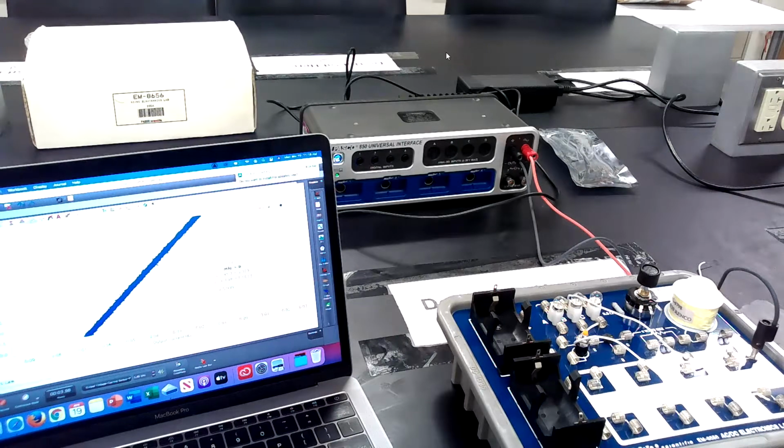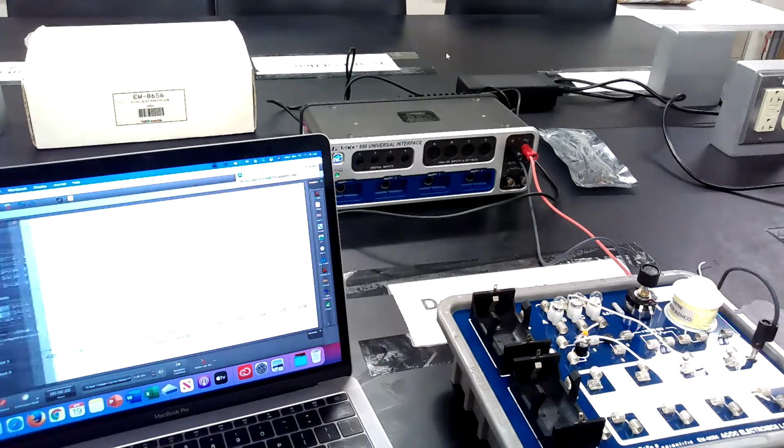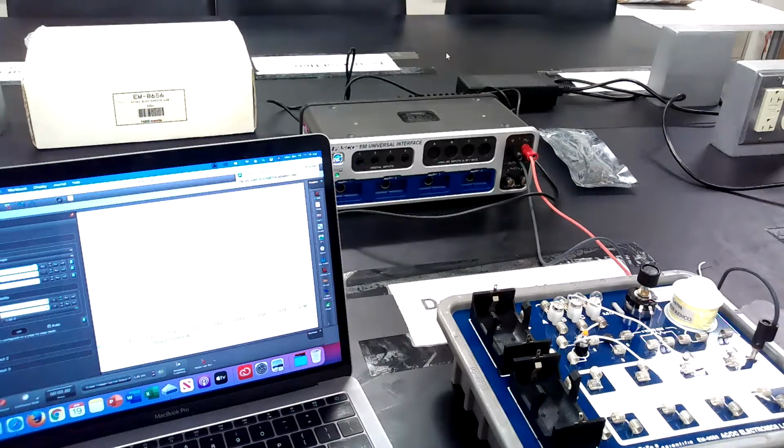All right. So let's take our previous result. We are going to erase that. I'm going to try to center this a little bit too. Okay. And I've got to make some modifications. My signal generator, the way it's set up, I can't use it that way. So I'm going to change this to 0.1 hertz. That means that every 10 seconds, it's going to go through one cycle. And I'm going to reduce the sample rate, the rate at which it takes data, bring that down to 40 hertz. It says 50 hertz in the lab. 40 hertz is where I am right there.